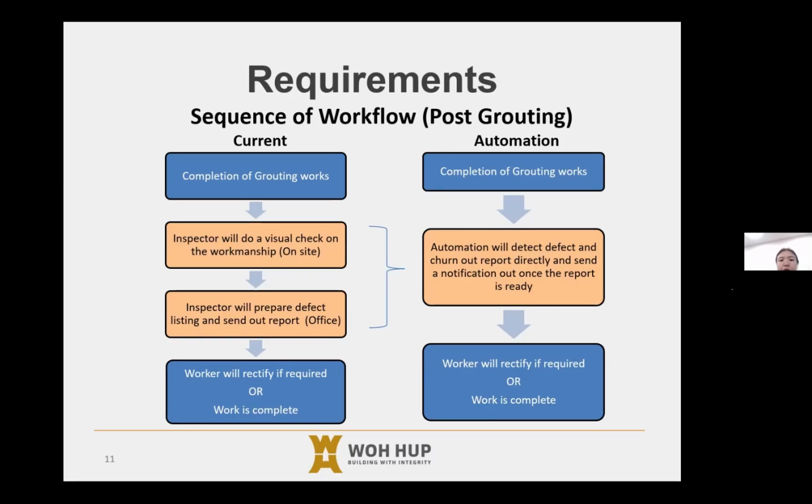But if there are still defects that need to be rectified, the inspector will have to do the same procedure as the pre-grouting work sequence. They will have to issue a defect list, take photos, then come out with a report. From here, we are also looking to streamline. So the system should be able to capture photos, list down the defects, and come out with a report at the same time.